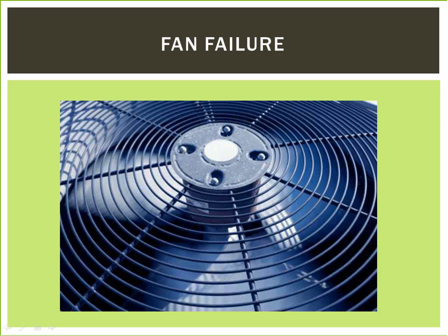Fans will cycle on and off with the compressor. The symptoms of fan failure are very much the same as plugged filters or coils. If the condenser fan does not come on, high side pressures will rise. This will put excessive strain on the compressor and reduce the efficiency of the system. Once again, left unattended, this condition will lead to the rupturing of the system and/or compressor failure. Evaporator fan failure will stop airflow through the evaporator and cause it to freeze up. Freezing will continue all the way back to the compressor and could lead to compressor failure.